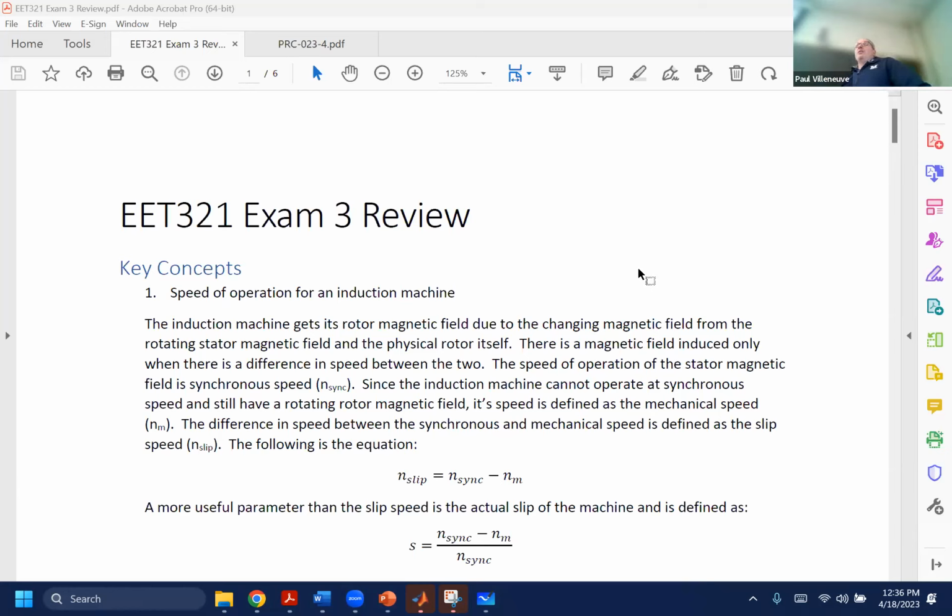And then before they could refeed from Milford, which it should auto refeed, maybe there was just a problem. They did have a problem with the switch at the top of campus that would prevent them from doing that, because that 46 kV line should just, it's not a recloser, it's called a sectionalizer. Yeah, they have sectionalizers that can come around and reconfigure things. And so I'm wondering if that pole that went down must have had the sectionalizer. So there's an accident that took out a 46 kV line. And that's why it's a problem.